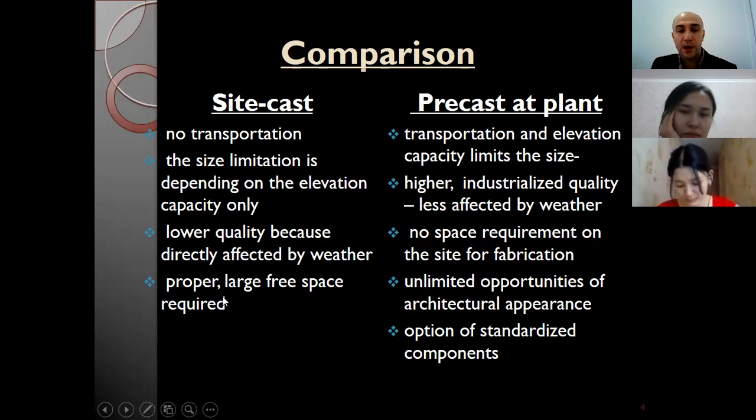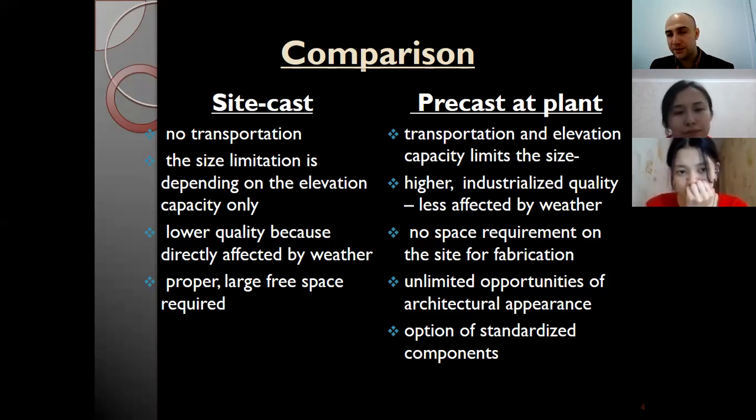Large free space required. So what about space requirement? On the construction site, we need to store the materials like formwork, like reinforcement. So we need special places for the big brigades where they will work and how they will work. All these questions require big spaces on the construction site. That's sometimes not required when we use precast or modular construction.